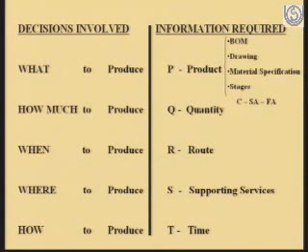How many stages of manufacturing will there be? Is it single-stage or multi-stage manufacturing, and also we want to find out whether it is at the component stage, that is C, or a sub-assembly stage, or a final assembly stage. So where will this component go? The product should be broken down hierarchically into different levels, that is final assembly, sub-assembly, components.